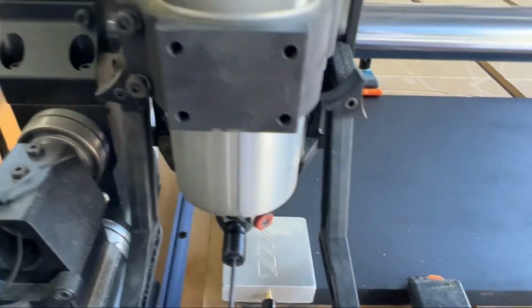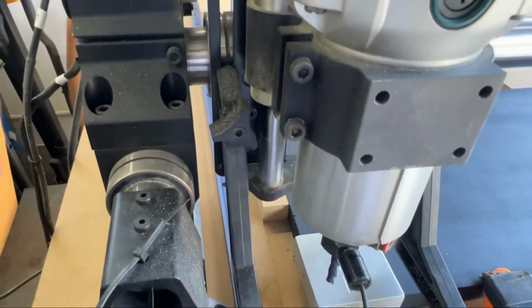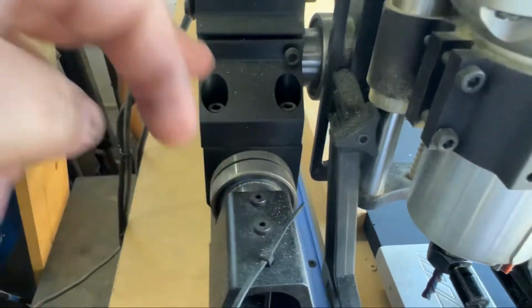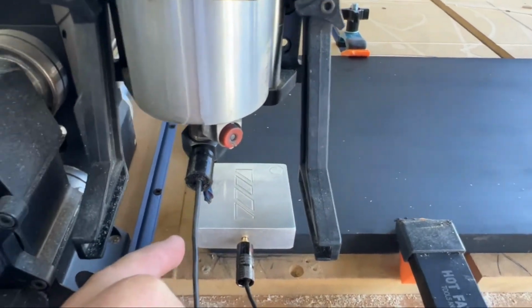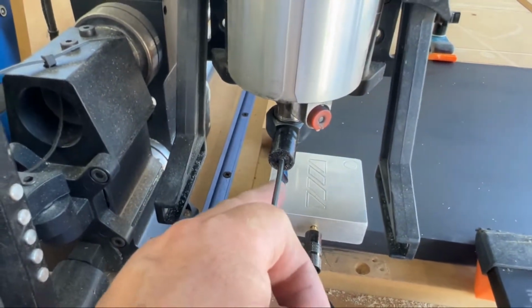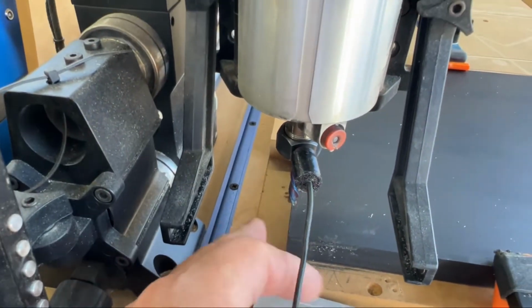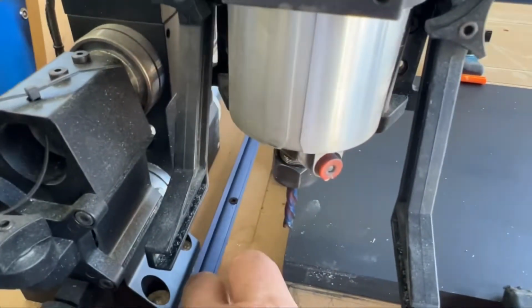So, remember what we were talking about earlier, home machine? If I home the machine, this bearing would be resting against here. That's home for the machine. But now it knows, because of the measurements of this block, that this is always going to be 0. 0 is going to be the corner of my material. It's always in line, so it always knows what the starting point is.